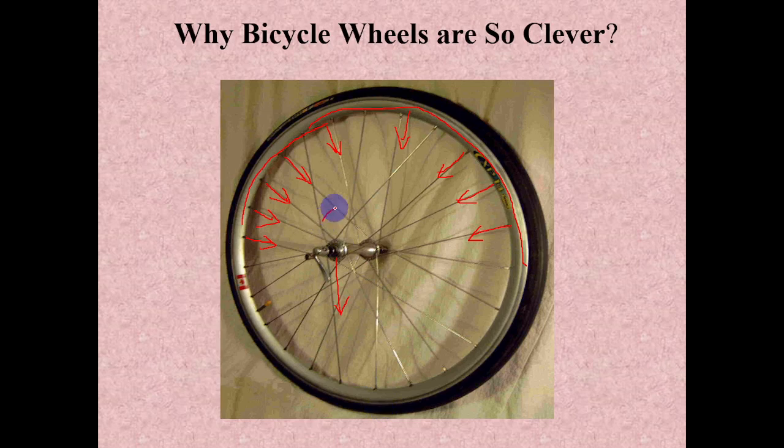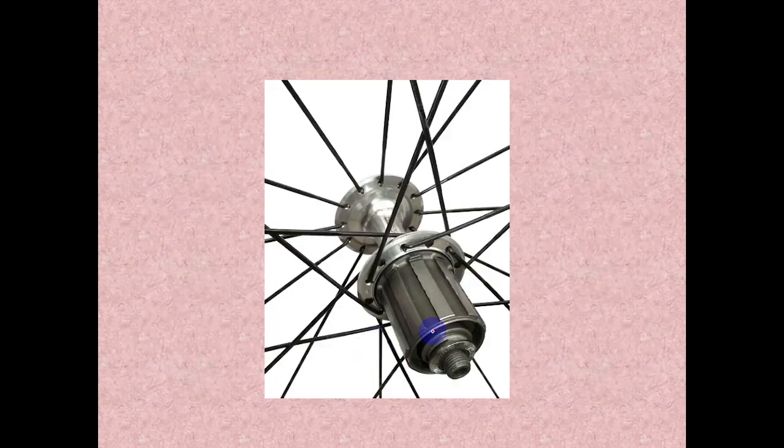In the same way, we are applying one torque also here. So how is this torque transferred as pure tension to these spokes without any bending? That we will see. If we closely see the hub here, when I apply some torque, these spokes are not connected concentrically to the hub.